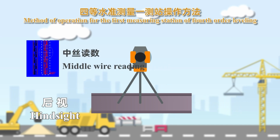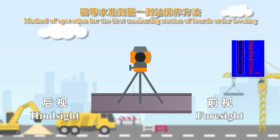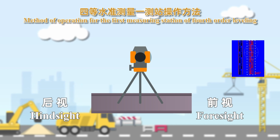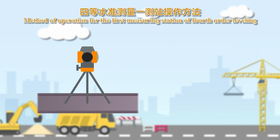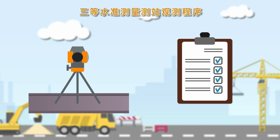3. After alignment, the red surface of the leveling rod is viewed, and the middle wire reading is read. 4. After alignment, the black surface of the leveling rod is viewed, and the lower wire, upper wire, and middle wire readings are read respectively after the instrument is accurately leveled. 5. After alignment, the red surface of the leveling rod is viewed, and the middle wire reading is read. The above 4-level observation procedures are often abbreviated as after before, or black red. After the observation results are recorded and calculated to meet the requirements, the instrument can be relocated to the next station for measurement. Otherwise, necessary re-observation should be carried out.